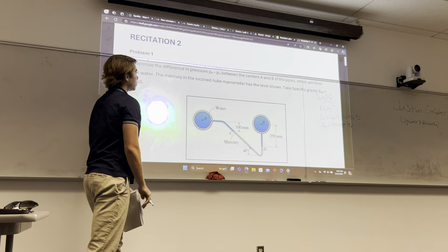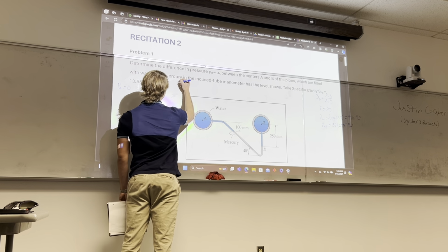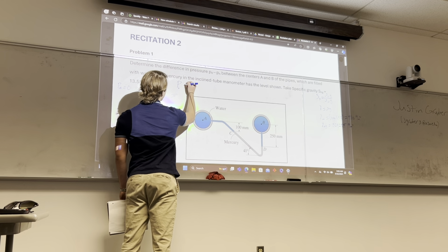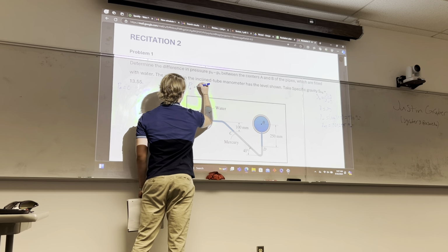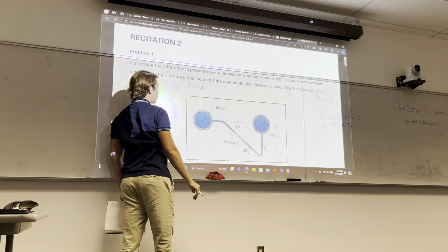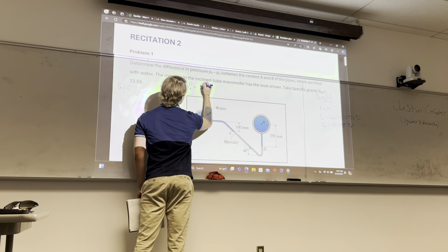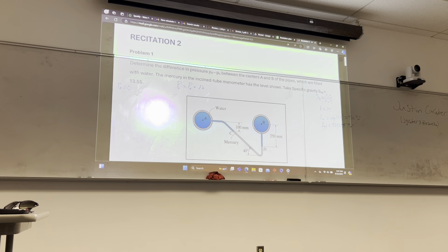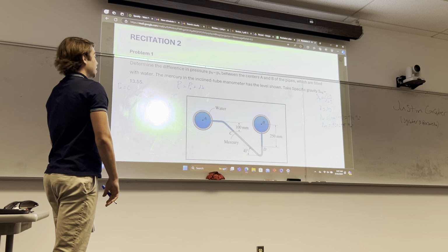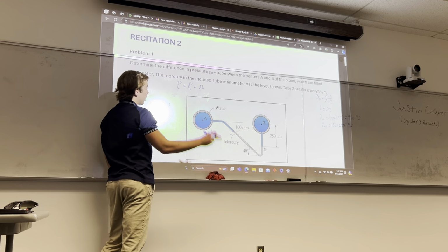And now recall your standard point-to-point pressure equation as P at some point, I'll call I, equals your initial pressure wherever you're starting plus rho GH. And in this case, that rho GH can be replaced with gamma. It's the same thing. In practice, I like to just use rho GH instead of gamma because it's just one less variable I always have to remember. But for this, we do that. So this one's pretty easy. So to start off, we know the pressure A is 0.